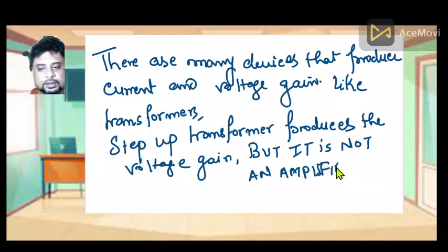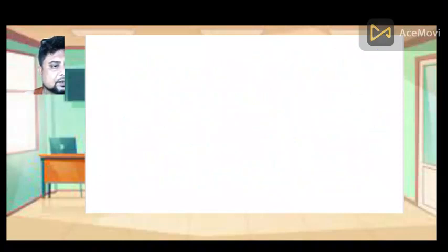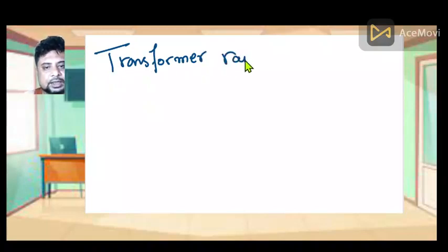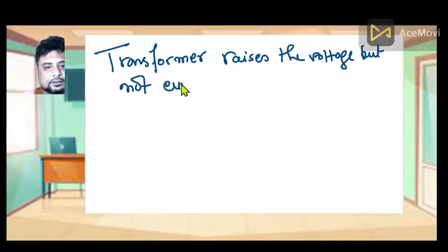It is not an amplifier because it is not producing power gain. If it is increasing the voltage, it is reducing the current. So you must take this into consideration. A transformer raises the voltage but not the current. And a step-down transformer produces a current gain, not voltage gain, so it is not an amplifier.